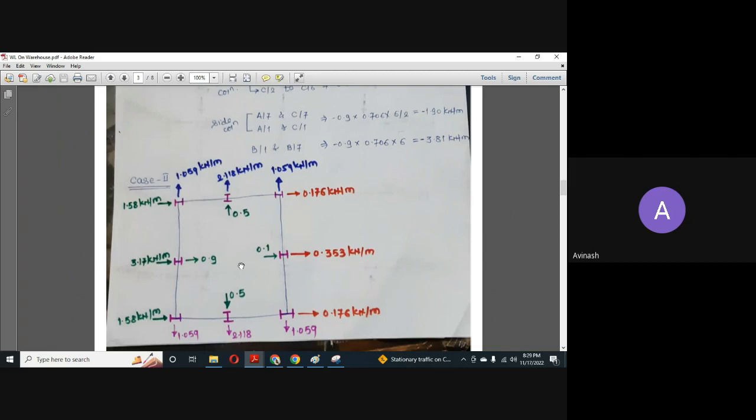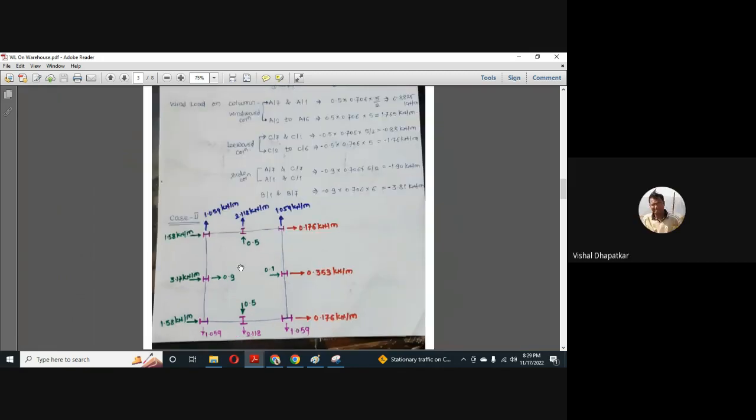तो सॉफ्टवेयर में भी इसी तरह डालना पड़ेगा सर? सॉफ्टवेयर के अंदर जो लोड इनपुट करेंगे, तो इसी तरह डिस्टेंस कैलकुलेशन करके फिर एंटर करना होगा उसके अंदर? Yes. For closed structure you have to enter like this only. For open structure you can generate load in the STAAD itself. You don't need to calculate all these things. If you are applying load for the closed structure, then you have to calculate like this only. For open structure you can generate the wind load command in the STAAD, and it will automatically consider the load based on the section sizes provided.